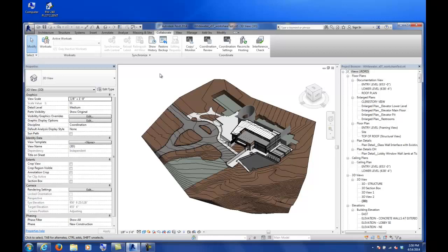Revit is designed for that purpose, but in order to work in that manner, there's a couple things that you need to know. Number one, essentially what you're going to be doing is exactly what you just heard Jefferson talk about: there's going to be a wireless router that's going to be tested here, set up in the studio, that's going to be connected to a hard drive. That hard drive is going to be the place, when I talk about it in this tutorial, where you're saving your central model. That's where the central model has to be saved, on that hard drive.